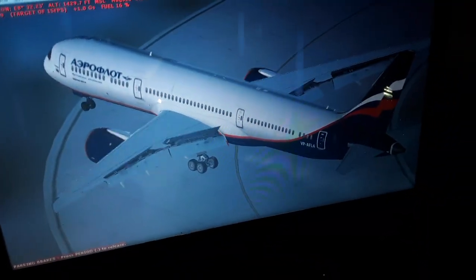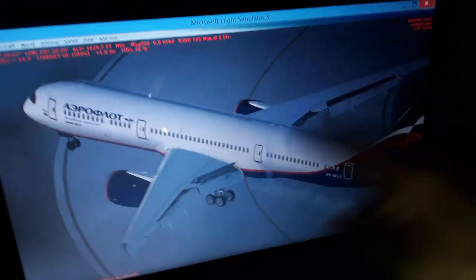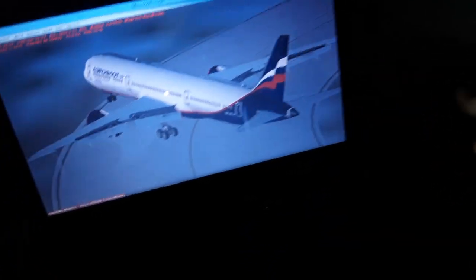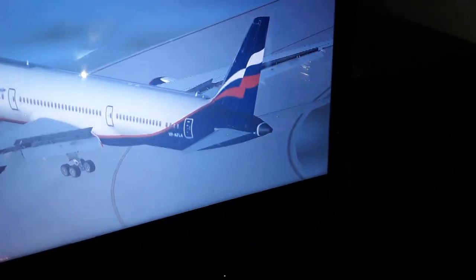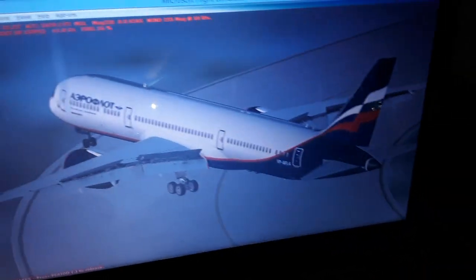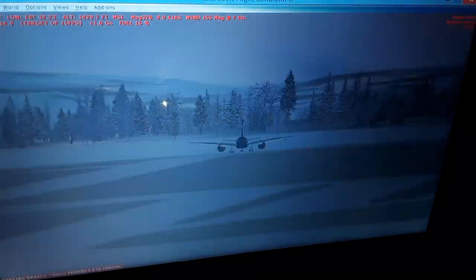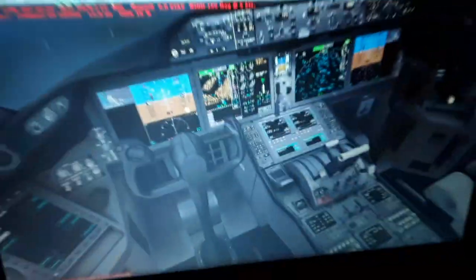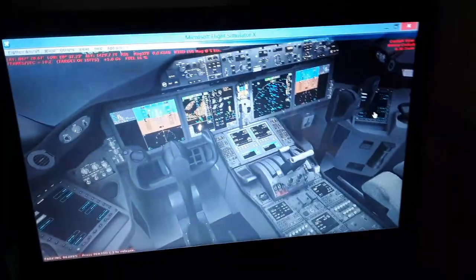So we have here the mean aerodynamic chord. We have the center of gravity here, and also the yawing axis of the aircraft. So the yawing axis, to yaw the aircraft, you use the rudder in flight with the rudder pedals over here, also the forward nozzle. So you use the rudder pedals like this, left and right, to control the rudder in flight.